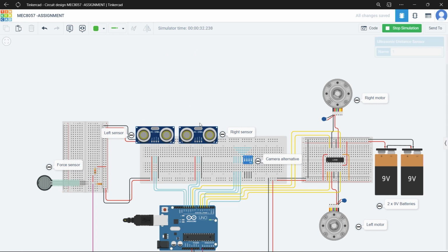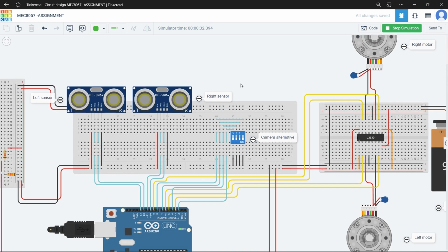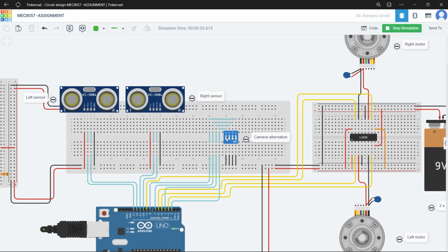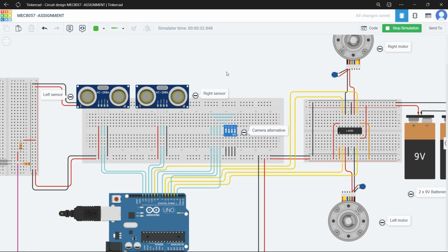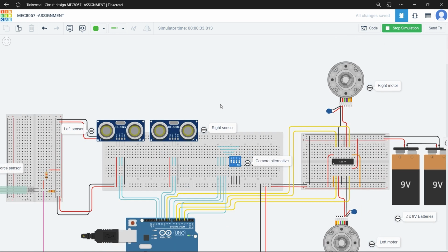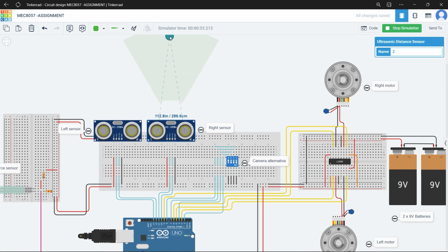Now the pre-programmed movement is done, and there are 4 switches for camera 1. If we turn on the camera and the distance sensor value is less than 200, the motor stops and waits for the next process. The motor stopped.